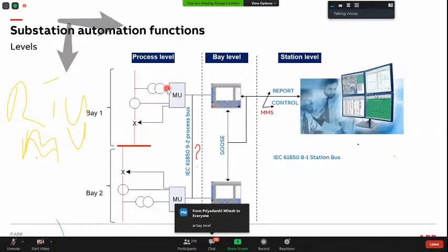Same here for voltage. Once you cross here, it's digital, ones and zeros, in a specific format. It's called the IEC 61850-9-2 process bus. There's a standard for how your packet should look. So this has become digitalized here. Analog ends at this part, and you have digital here and here as well. This is for transmitting current and voltage in a specific, digitalized format.